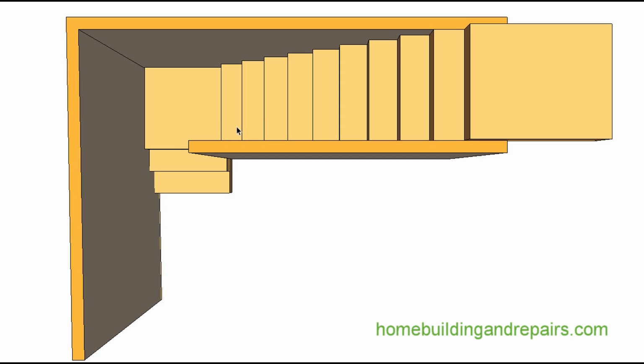You eliminate a tread, and then you'd have to rebuild the stairway, obviously. But this would allow you to get a wider stairway. So if you had a 9-inch step and you eliminated one of the steps, you would almost have 10 inches, I believe, if I do my math right. This would be close enough to a better stairway.